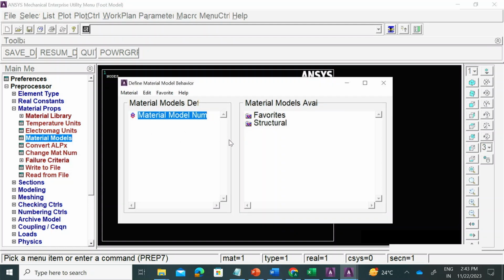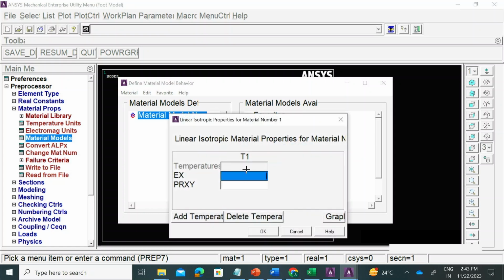So I'm going to hit on the material models and go to linear, elastic, isotropic, and go for a material property, let's say 10,000, and just make it 0.4, right? 10,000 is a little high property, it's almost going towards the cartilage or bone, so let's keep it to 1000 maybe, right? So I'm going to delete 10 and just update this to 0.4. Okay, so this is done.